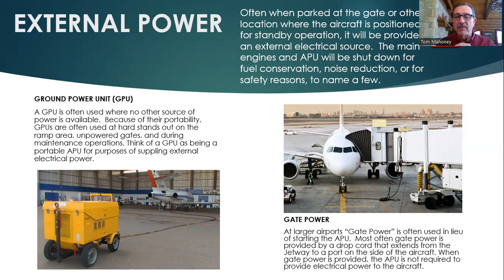So we've just landed the aircraft, we're exiting the runway, we're taxiing down the taxiway. Before we get to the gate, we would actually start the APU, because in anticipation of shutting the engines down, we get the APU up and running as a backup source of electrical power on the aircraft. So the aircraft stays electrically powered while there are passengers on board. We taxi the aircraft up to the gate on the J line. Then we pull the jetway up to the aircraft. At the same time, the ground crew is giving us a signal that they have plugged in the external power.